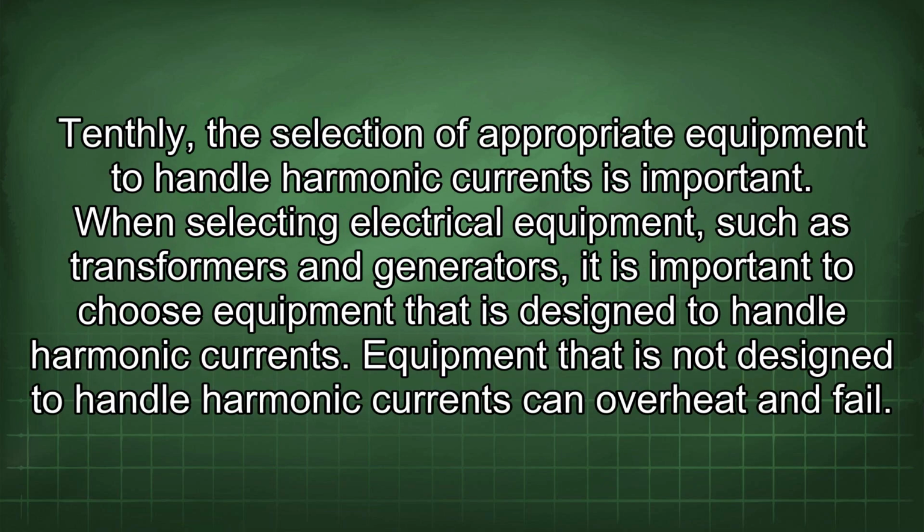Tenthly, the selection of appropriate equipment to handle harmonic currents is important. When selecting electrical equipment, such as transformers and generators, it is important to choose equipment that is designed to handle harmonic currents. Equipment that is not designed to handle harmonic currents can overheat and fail.